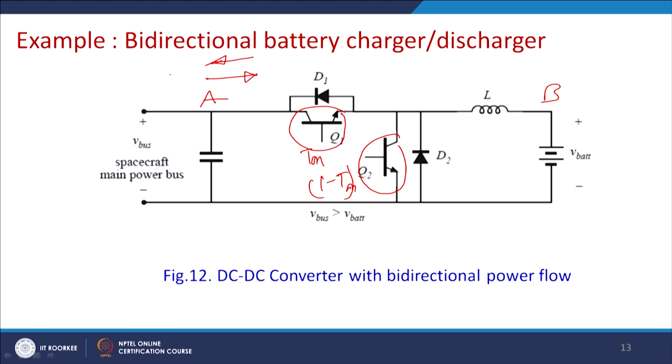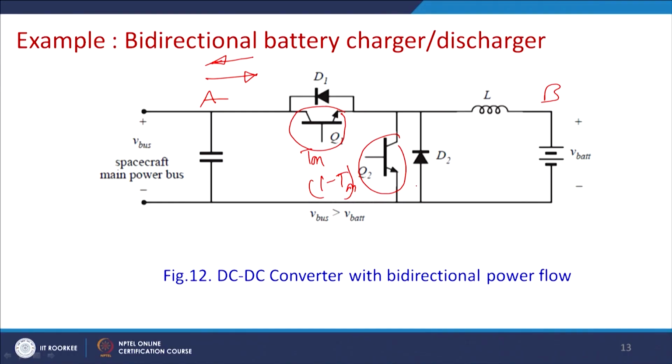So, let us understand what happens. Now, in most of the cases we require to buck the voltage to charge the battery. Battery bus is connected at a little bit higher voltage. So, for this reason, this bucking operation is done mostly by Q1 and D2, and we can put in the same way here a MOSFET, which can have a body diode.